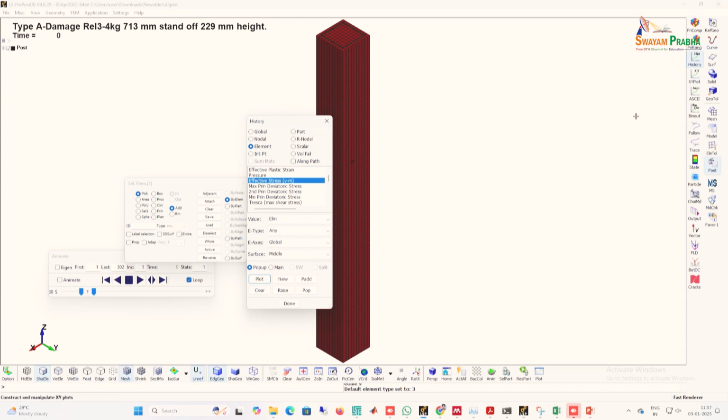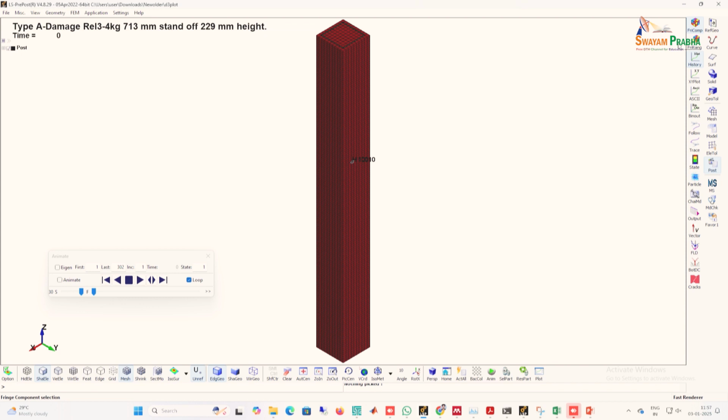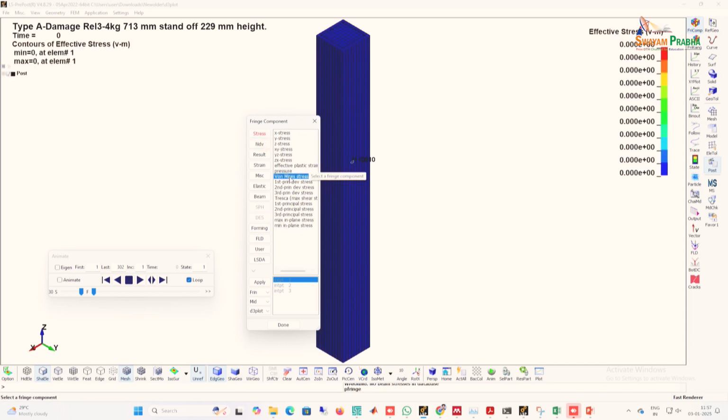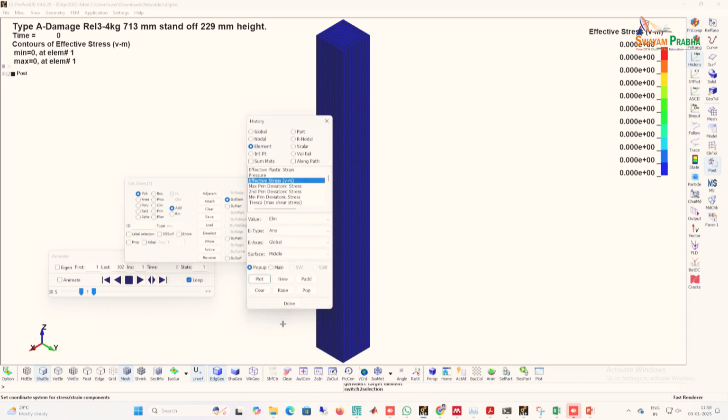And then you can run, for example, you want to check whatever your, this is where knowing plasticity helps, because then you know which parameter to check, whether you want a strain parameter, are you interested in the effective plastic strain. There are non-defined NDVs. So let's say you want the von Mises stress, which is the most commonly used one. First principal and second principal is also used,